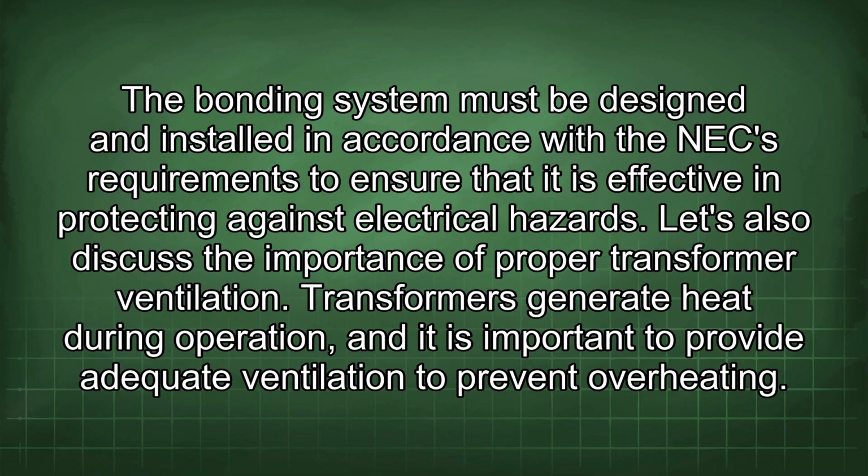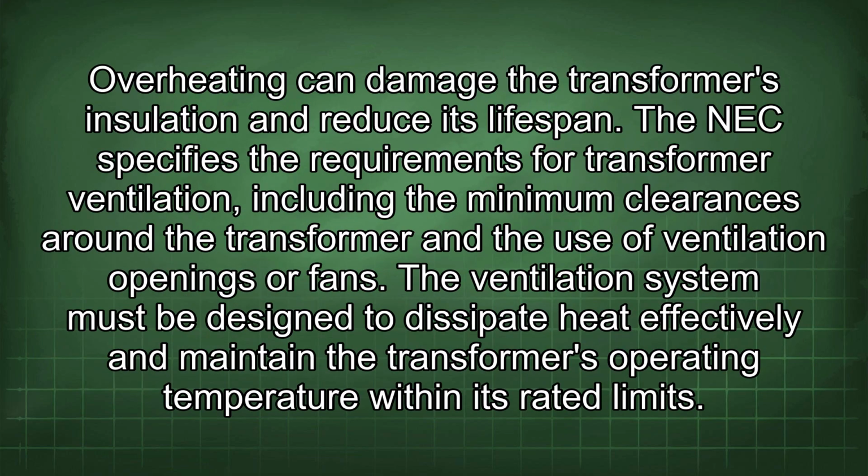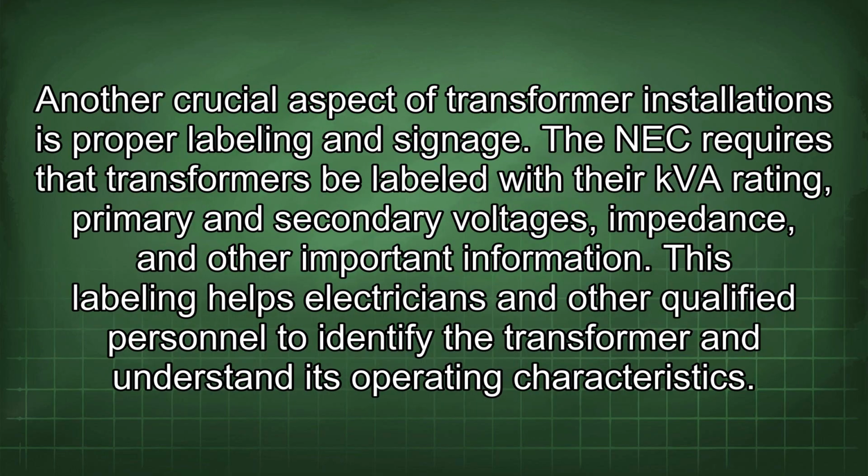Let's also discuss the importance of proper transformer ventilation. Transformers generate heat during operation, and it is important to provide adequate ventilation to prevent overheating. Overheating can damage the transformer's insulation and reduce its lifespan. The NEC specifies the requirements for transformer ventilation, including the minimum clearances around the transformer and the use of ventilation openings or fans. The ventilation system must be designed to dissipate heat effectively and maintain the transformer's operating temperature within its rated limits. Another crucial aspect of transformer installations is proper labeling and signage.